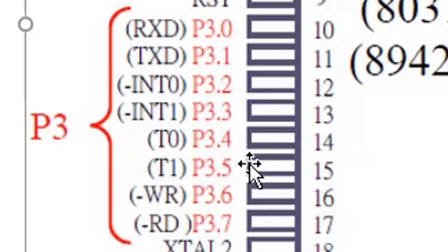Say for a counting operation, some signal is given here, say a particular square wave. For every high portion of the pulse, it will give a particular pulse into the timer, and that will be incremented by 1. So here this is used as the counter. Counter means if we give 1 pulse here, the timer will be incremented. Better we should call it a counter, not a timer. So when C/T is logic 1, better we always mention it as the counter.